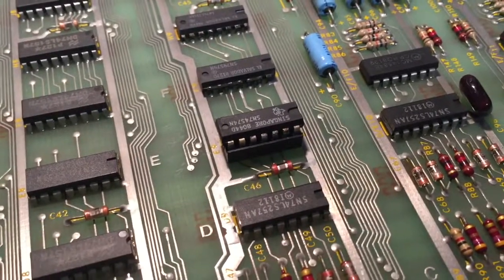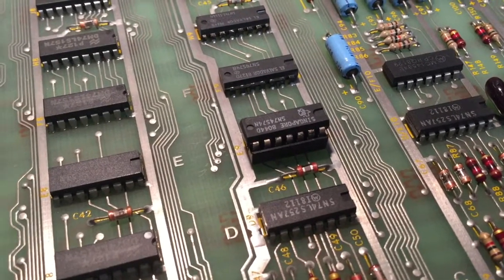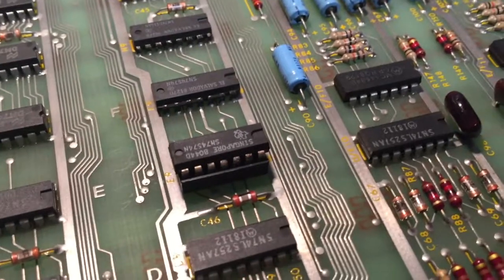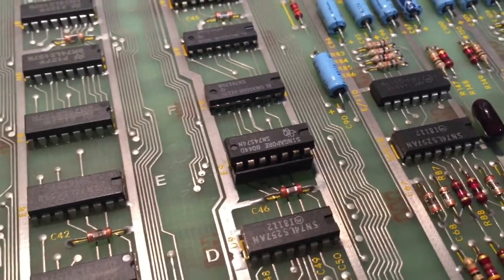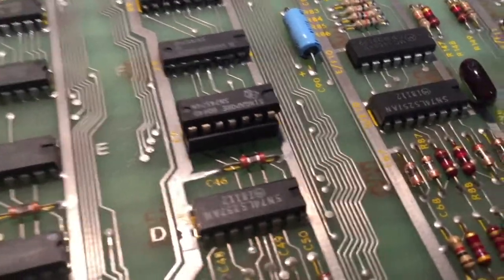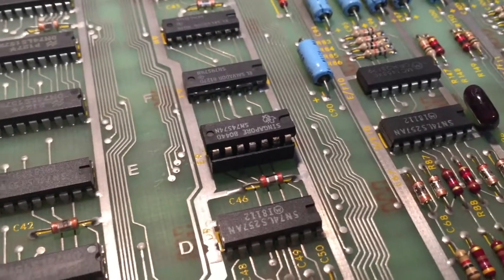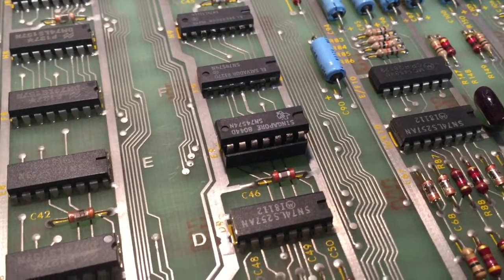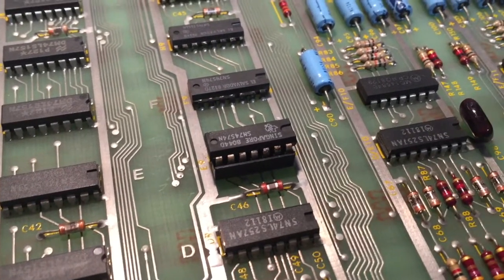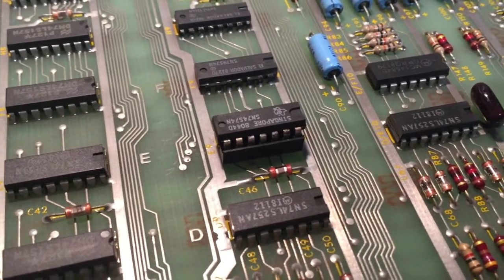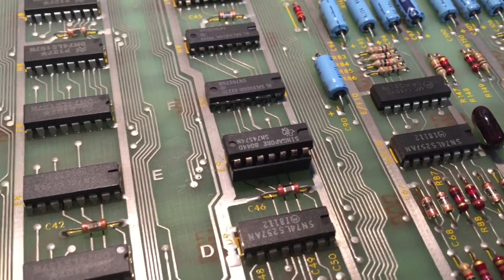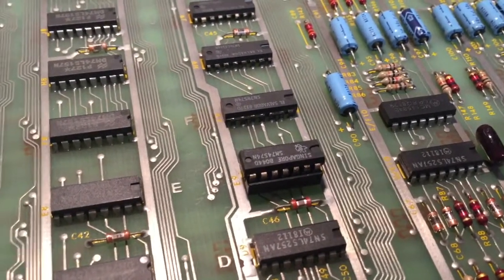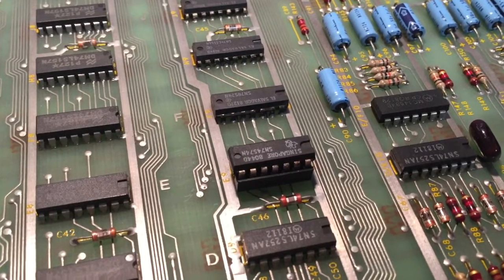So again, to prove that a complex logic IC like a flip-flop isn't working correctly, you have to look at it with a logic analyzer, and hooking that up sometimes takes a longer time than just replacing the part. But we don't actually seem to have a problem at the end of the circuit.